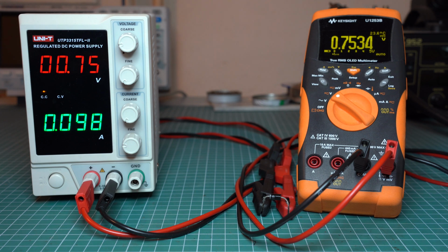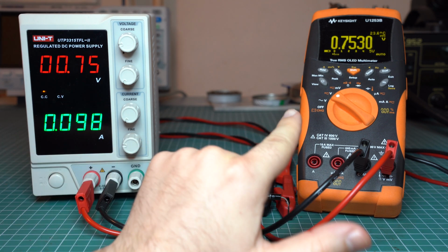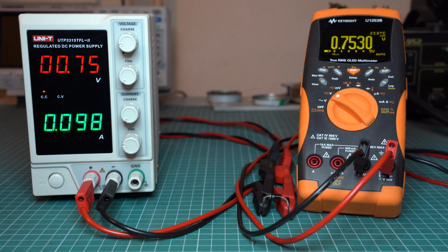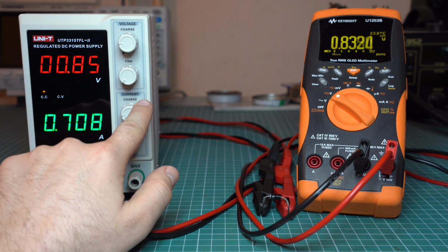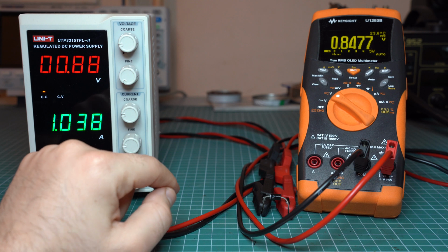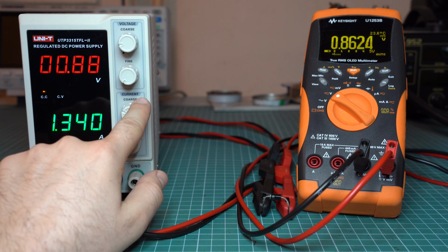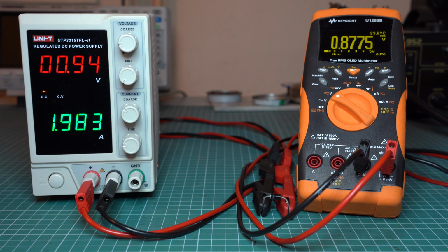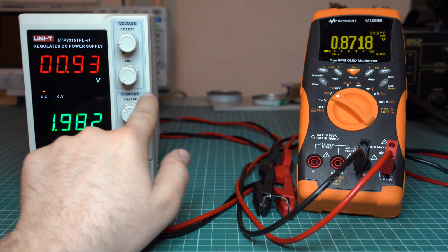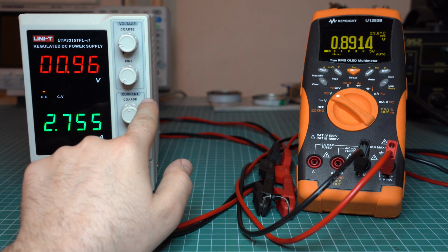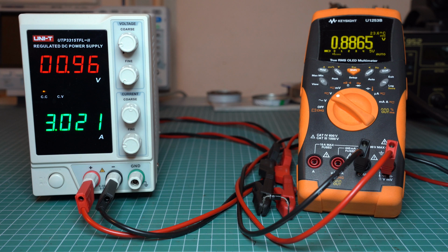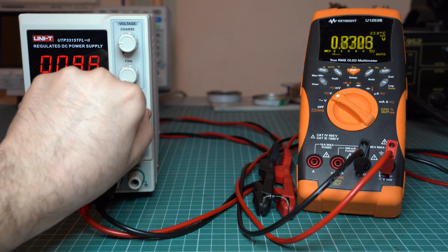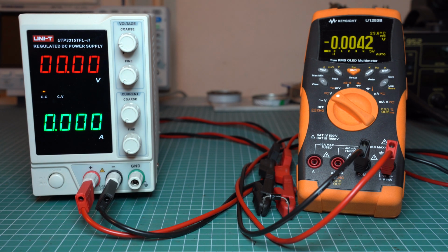Now, at a significantly higher current, or around 100 milliamps, we can see that the voltage drop is not significantly higher, so the rise in voltage is definitely not directly proportional to the current. So we can keep going. At 1 amp we have around 850 millivolts. 2 amps, 870 millivolts, and we can go all the way up to 3 amps, which is the maximum current for this diode. And at 3 amps we have 890 millivolts. So this proves that the diode is indeed non-linear. And if you don't believe me, we can put all these values into a table.